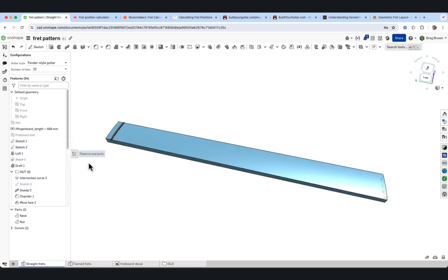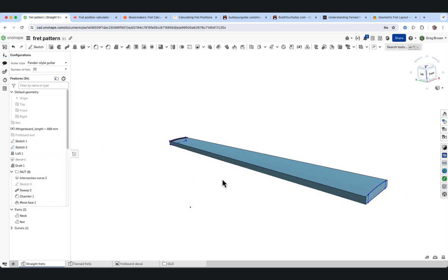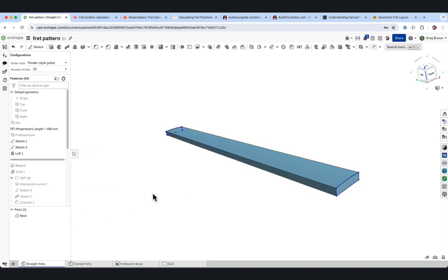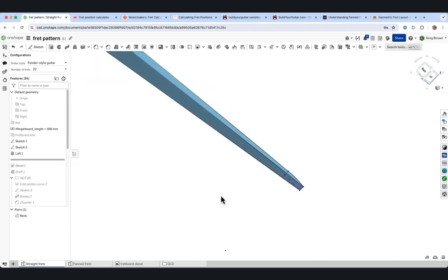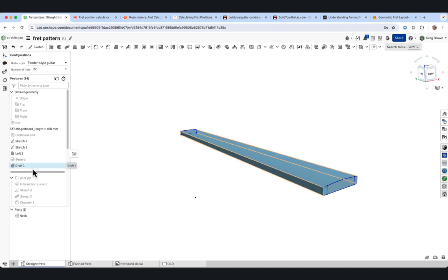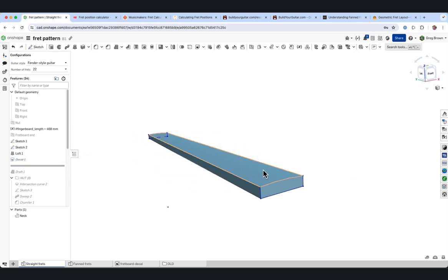I created a couple of sketches, and I'm going to highlight them in blue because that's what you should do too. So I lofted between those two, and then I drafted it to provide some taper. Now I could have done that taper as part of a loft by creating different size profiles, but I wanted to play a trick and show you why I did that separately. So if I do a loft between two equal sections, I could have done an extrude as well. Right, I could have done a sweep. There's many ways to do this.